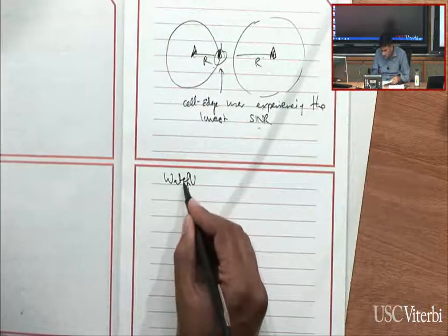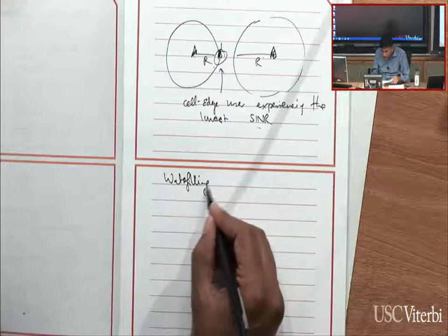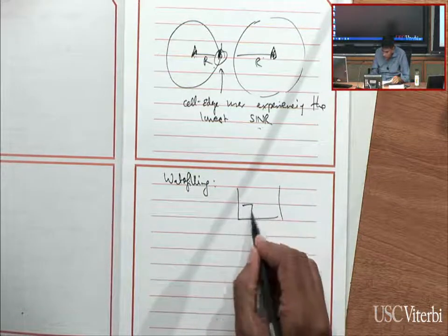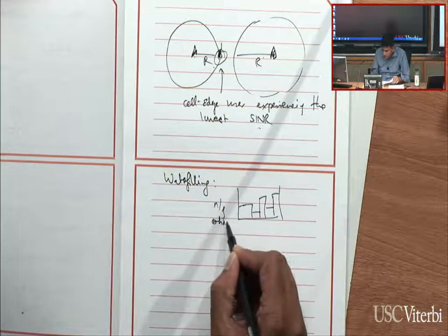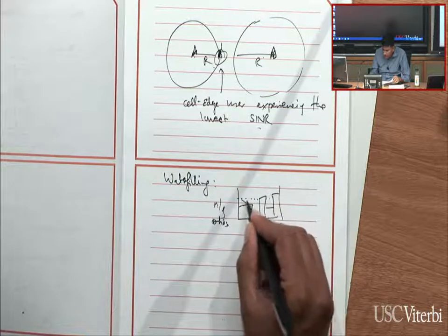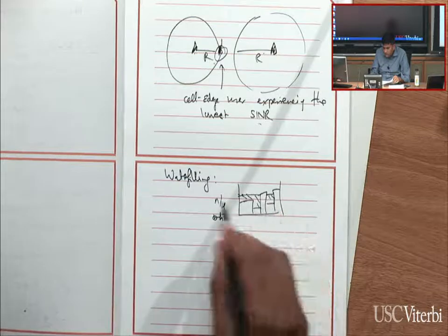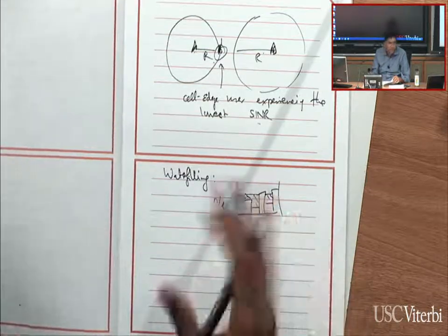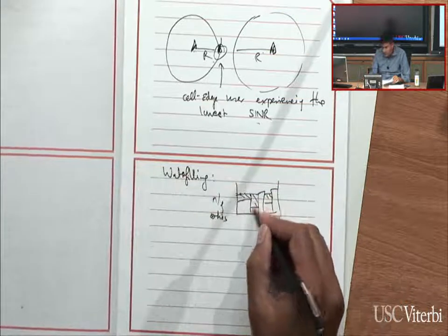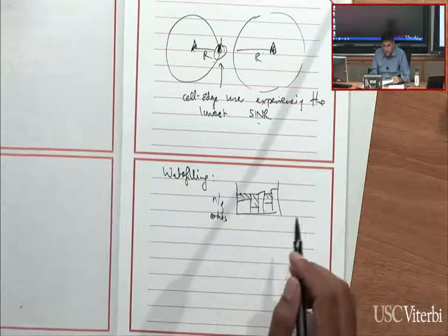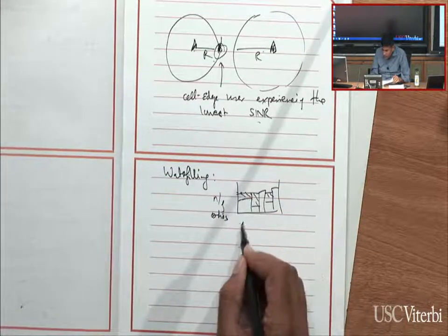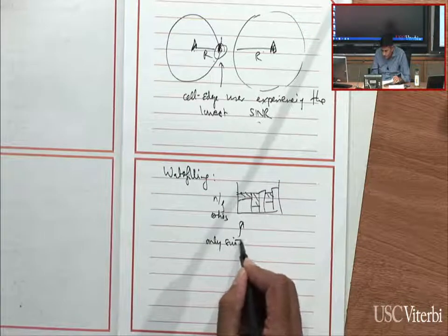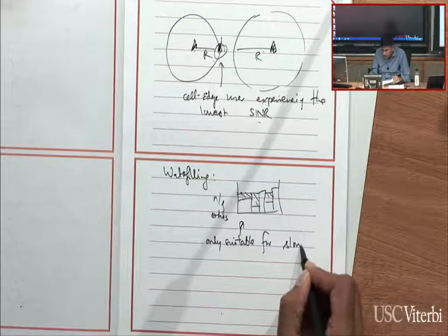And that deterministic view, for water filling, just said that we have a bunch of channels, here are their different noise to gain ratios. And we can basically figure out what power level to fill by choosing that water level in such a way that it uses up all the power, and you're delivering power to each channel. That's the gap between the water level and the noise to gain ratio for that channel. This standard water filling is only suitable for slow fading channels.